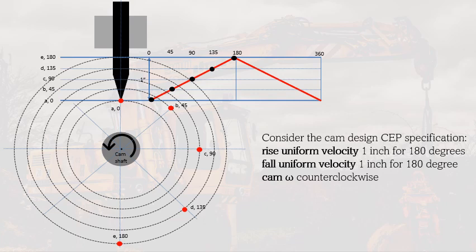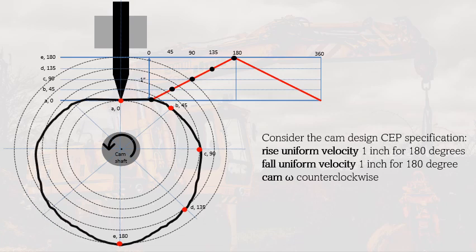If you're going to connect these dotted red lines using a French curve or a smoother curve so that it will be perfect, we will generate almost like this kind of profile. So this represents now the cam profile. As you can see, for a knife edge, the cam profile is the same as the pitch curve. And since they have symmetry on the second part, we will just project this to the other half to complete the 360-degree rotation of the cam.